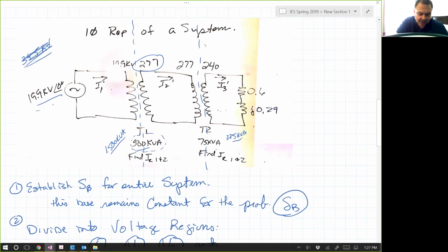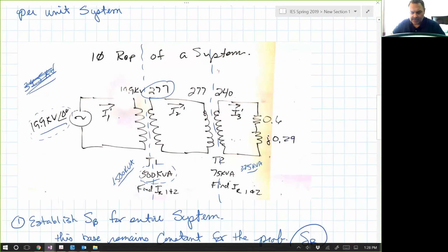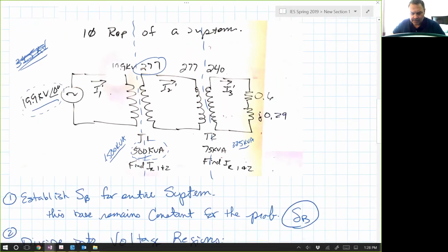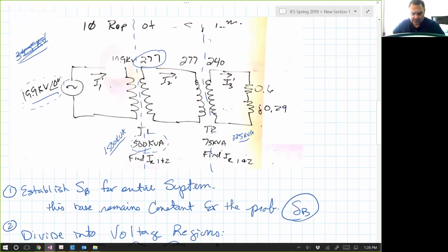Something that you're not used to yet that we're going to look at is our generators are also going to have an MVA rating, or a kilowatt rating plus a power factor. And you can get the kilowatt or the kVA or the MVA rating of the generator just by taking the kilowatt rating or megawatt rating and dividing that by the power factor. Okay. So first thing we want to do, we weren't given a generator here or a system yet that we're connected to, but we were given two transformers.